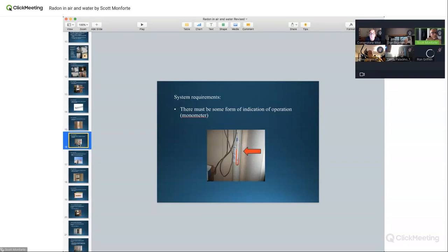That's all it is. Now, for me as a mitigator, even as a home inspector, when I look at that device, the higher that fluid goes, the more resistance I'm seeing below the slab. So generally, in new construction, with a lot of gravel under the slab, it's going to look pretty close. It might just be 0.5, 0.4, a little less than 1 inch of water column.